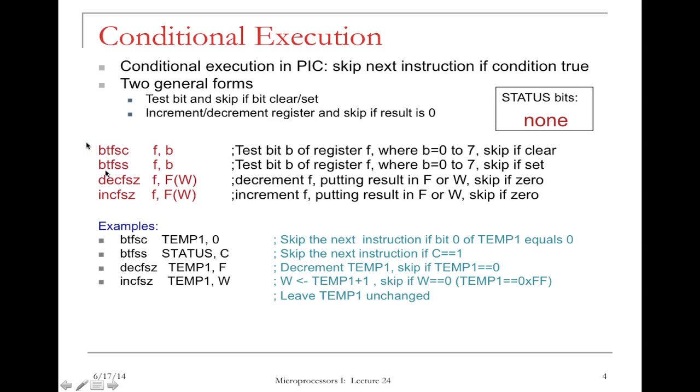Then the next one, BTFSS. The only difference is the last letter S. So this is to do bit test a register. I'm going to skip the next instruction if that bit is set, or if that bit is a 1. If that bit is a 1, we're going to skip the very next instruction.